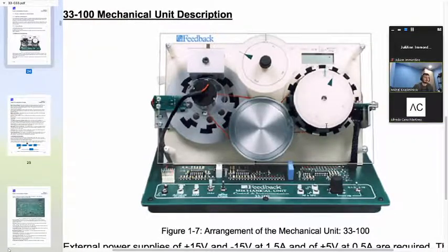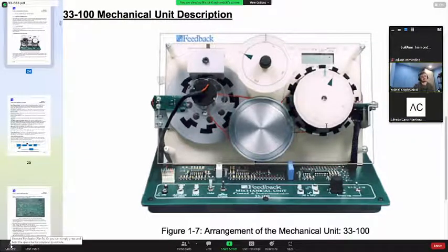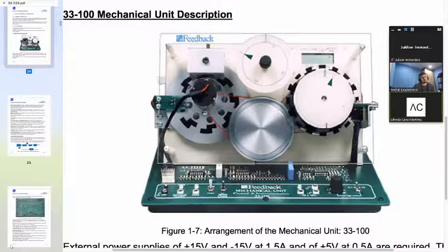Yeah. So that is why, with this transducer, the very first thing I tell students about this sensor, this 360 potentiometer, is the following. This thing is producing a voltage which is proportional to the position of the motor, in the sense that it will tell you how far away you are from a reference line. In this case, the reference line is this little thin needle on the top. Yeah, that's the reference line.